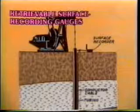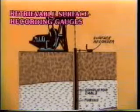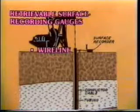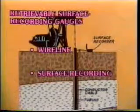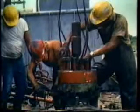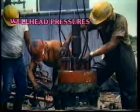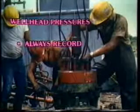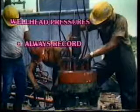Retrievable surface recording gauges are similar in most respects to the permanently installed type, except that they are run on a simple conductor wire line. Most use bourdon tubes for pressure measurement, although some use a quartz crystal. Even though bottom hole pressures are being recorded, it is recommended that wellhead pressure measurements be recorded at all times. Such data can be used as a check on bottom hole data and for wellhead deliverability calculations.